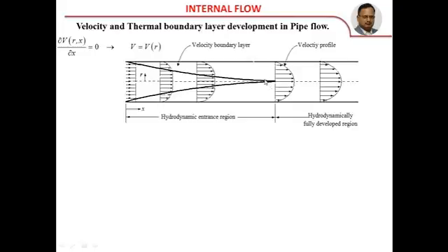The perception is, imagine this is one plate and that is another plate. So boundary layer development of a plate is like this, and for the top plate it is like this. Imagine an infinite number of plates surrounding one another, one over the other. The pipe boundary layer development you can understand.